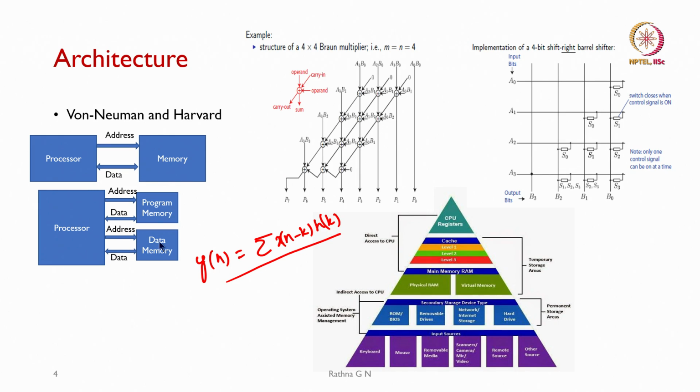So, what was decided? If we are talking about a filter, then we know that the filter is designed much earlier. In real time we will be using only those filter coefficients to pass the input through. So, these can be stored in our program memory, and the input data is going to come into the data memory, and then we can access them simultaneously.